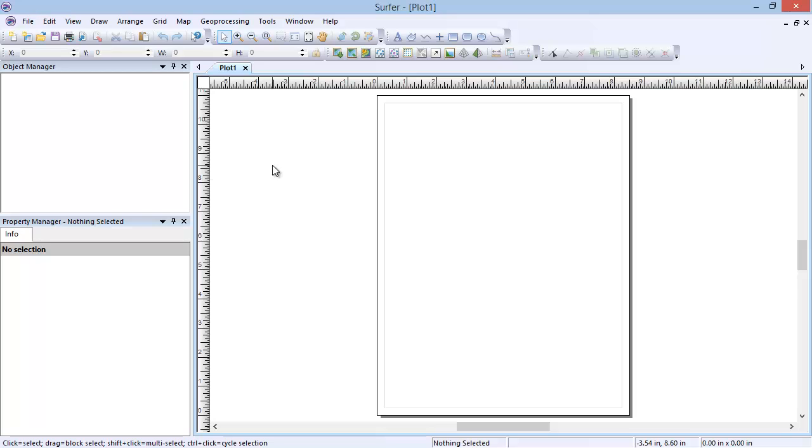Grid files can be created directly in Surfer from XYZ data files by clicking the Grid Data menu command. Or you can obtain grid files from other sources such as downloading them from the internet, such as USGS DEM files, or creating them in other software packages, such as Esri products. I will create an example of each map type.